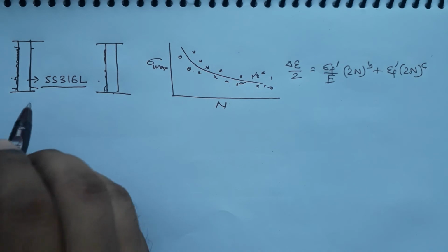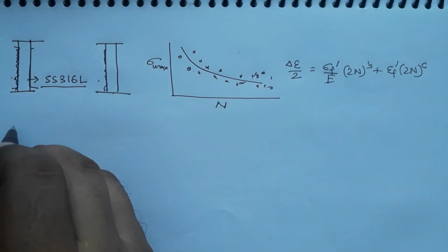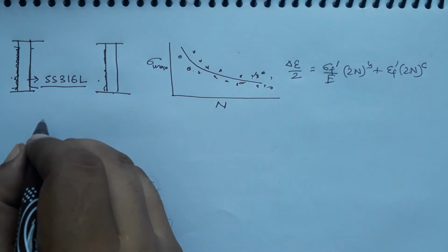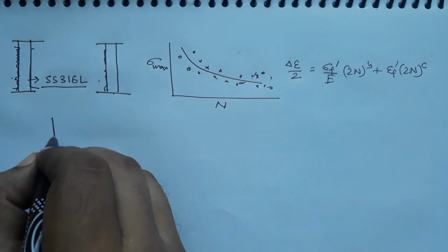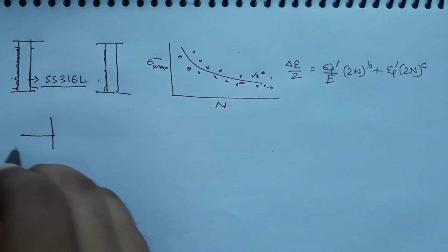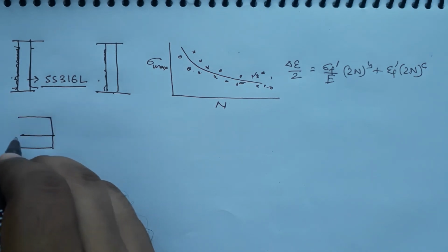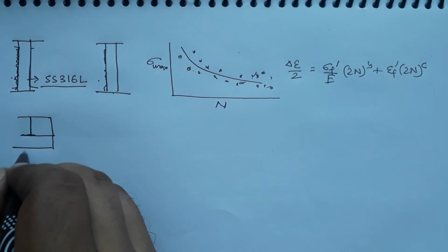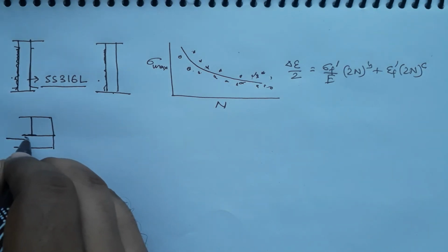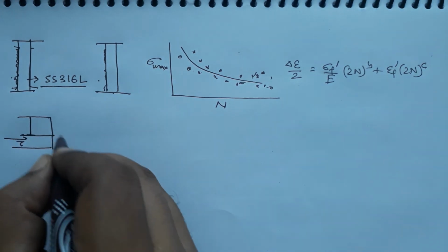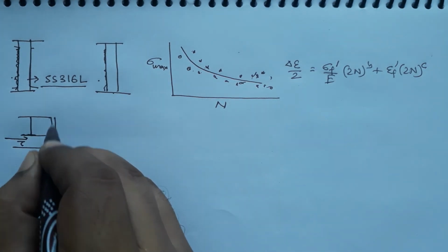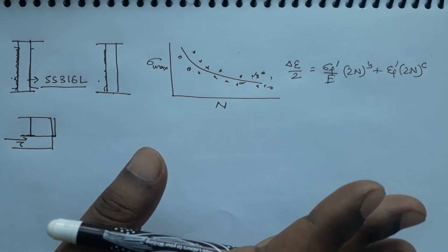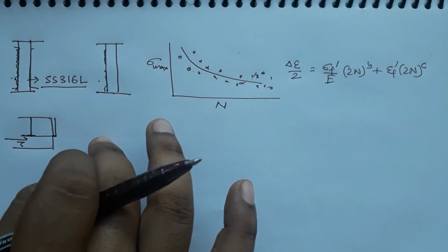So, we do that. What will happen in that case? The material, for instance, you are applying some stresses, and we know that usually the deformation happens because of shear stress, right. So, I have a dislocation like this, an extra half plane which is present downwards, and I am applying a shear stress. This dislocation will go to the surface, and on the surface there will be a step formation. This much we know, right. This will happen in monotonic loading.